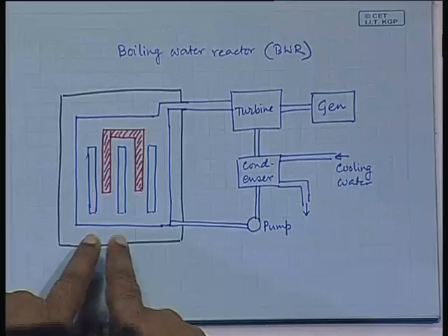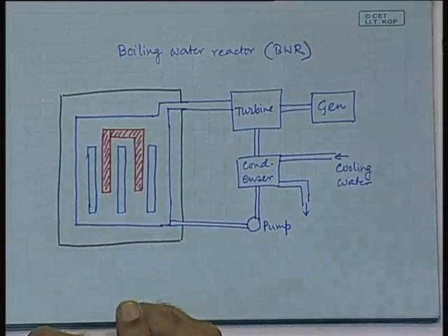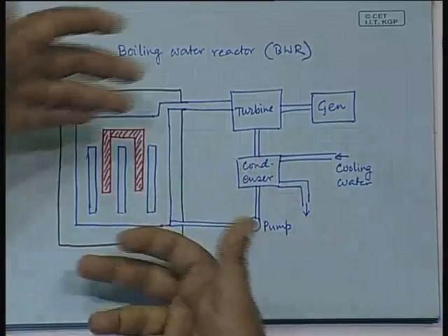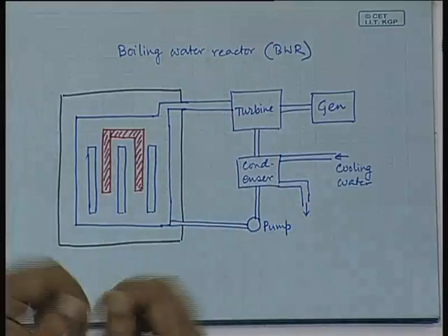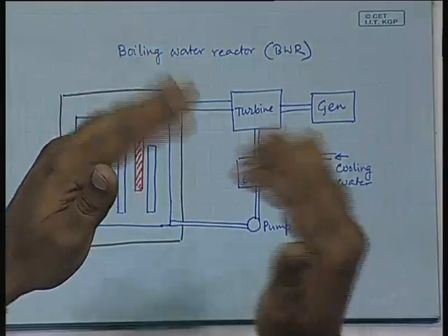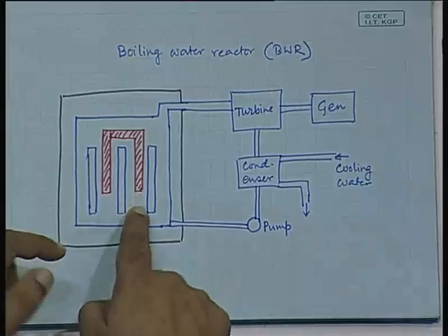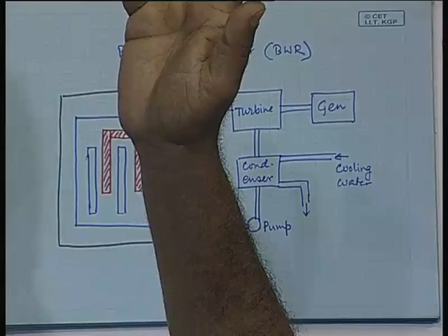Next possible step is there is another problem, because you are allowing the water to boil here. Because you are allowing the water to boil here, the temperature is low. Okay. The temperature is not very high, because here it is actually boiling. Depending on the pressure that you allow, it will not be 100 degrees, it will be higher, but not much higher. Okay. The water that goes out of this is allowed to expand a bit. That means the pressure is brought down. As a result, it goes from the saturated steam stage to superheated steam stage. In a boiler, what happens? In a normal coal fired boiler, you had the superheater where you add more heat to it. But here the place where heat is generated is inside here, where water is coming in contact with that, which at the time is boiling, and therefore you have to do something else to get into the superheated stage. And what is generally done is to bring down the pressure a bit, so that it goes into superheated stage. Clear?